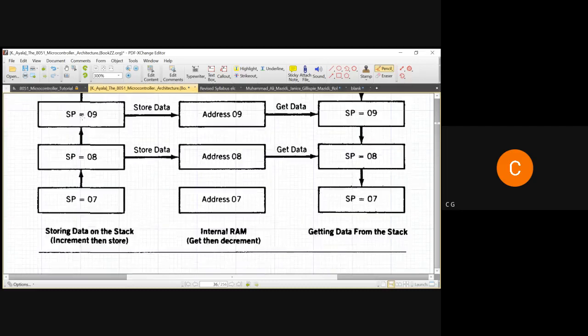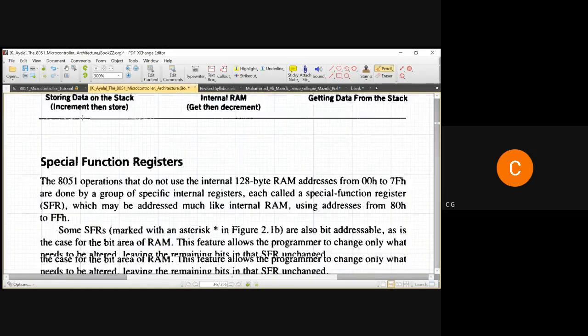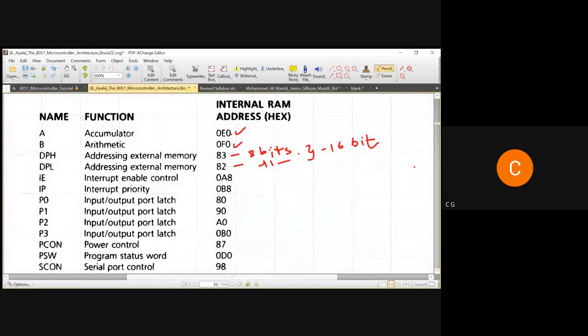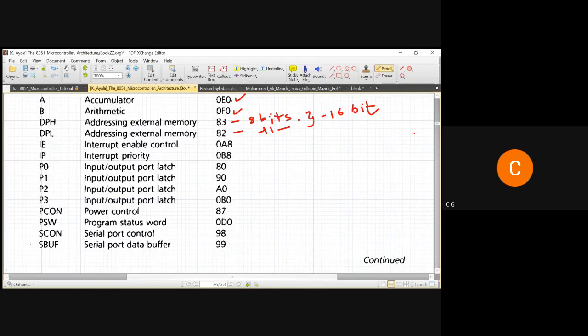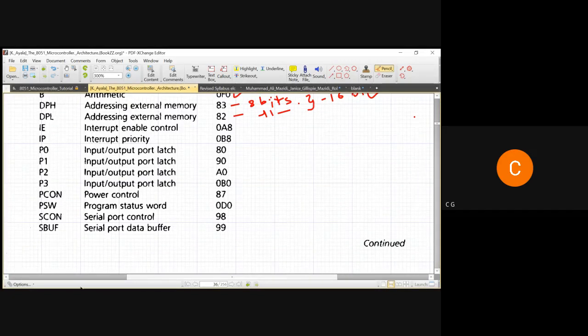It will destroy the permanent data or the data which is being used at a later stage by the CPU, right? So the programmer has to make sure that I want to use this much part of the RAM as stack. Otherwise, it can give you big trouble.